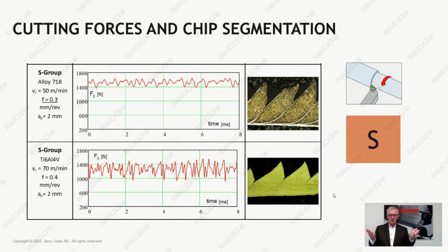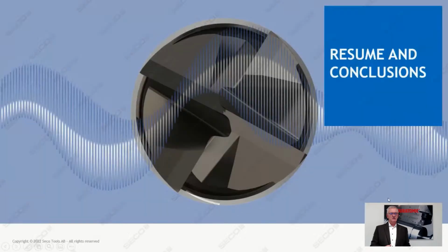And micro vibrations, you know, in most cases you don't even hear them, because people always talk about chatter and so on, and they say, listen, but with micro vibrations the frequency is so extremely high, you don't hear them. People don't hear them, but they kill cutting edges. Huh? And that's the whole thing here. That's why this insight is so important.